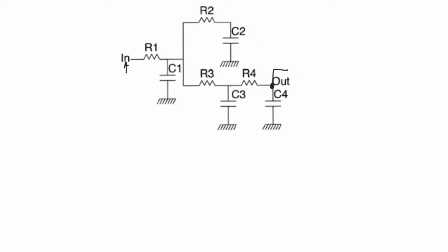It's actually pretty easy. What you have to do is that the time constant is going to be composed of multiple time constants, as many time constants as there are capacitances or capacitive nodes. So we go to the first capacitive node, and we find, first of all, of course, the time constant is going to contain the value of capacitance, and we multiply this by the resistance which is in common between the path from the input to the node at hand and the input to the output.